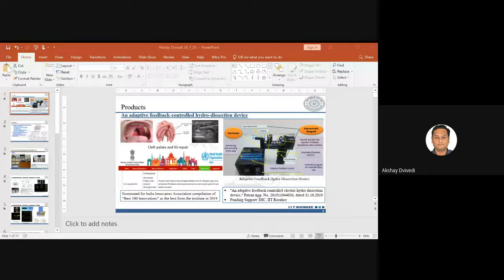Glass is hard and brittle. In that case, when you use any kind of conventional machining approach, things become very difficult. There can be a suggestion from someone who says, okay, glass is easy to melt. You can make a mold, and with that mold you can create whatever shape you wish to make. But the issue is that when we talk in dimensions of micrometers, getting the glass shaped to that specific size has huge problems. They are many. So those molding approaches cannot actually help here.